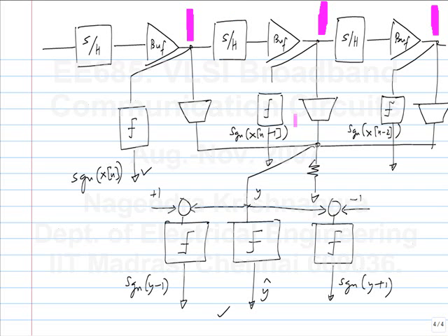Actually, if you look at this, this is simply a delayed version of this, and this is a delayed version of this, and this is a digital signal. So I can delay that using flip-flops. I don't have to load these points and determine the sign. So that's the idea. I can slightly optimize the circuit by removing these comparators.